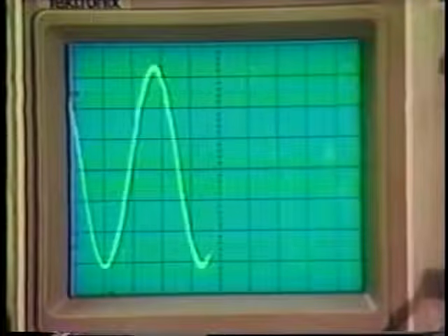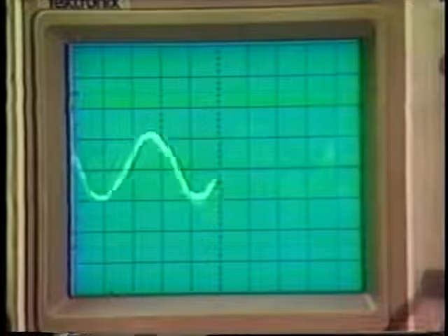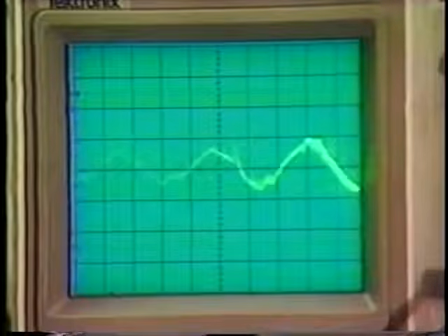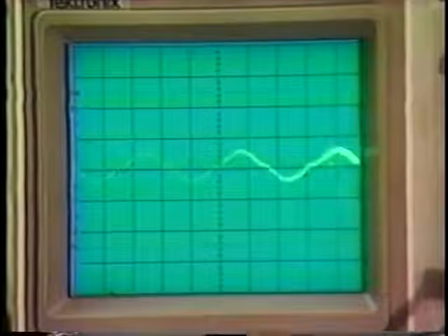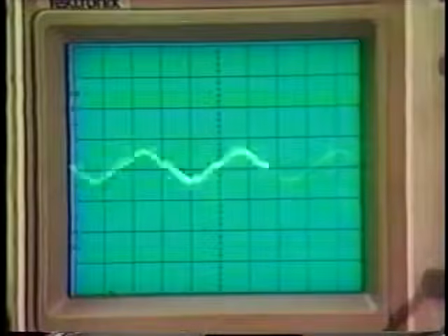When faults do occur, the power system no longer operates with beautiful sine waves and balanced phasors. At any instant in time, we may have voltages and currents going in several directions, with magnitudes and phase angles being imposed upon each other. Breaking the quantities down into symmetrical components helps us visualize the conditions.